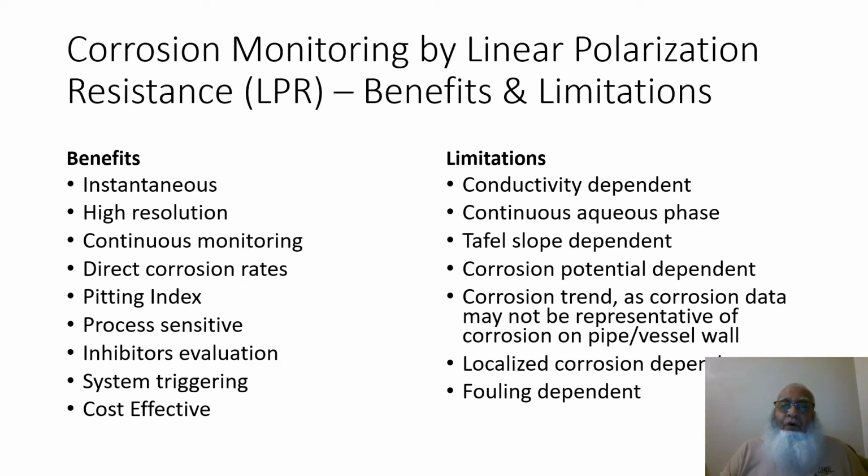It is Tafel slope dependent, and corrosion potential dependent. The corrosion trend data may not be representative of the corrosion on the pipe or the vessel wall. It's also localized corrosion dependent. It's also fouling dependent, meaning when the probes become dirty or fouled, this system starts giving you erroneous results.